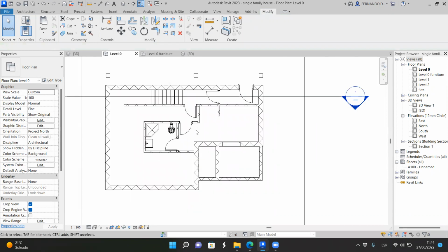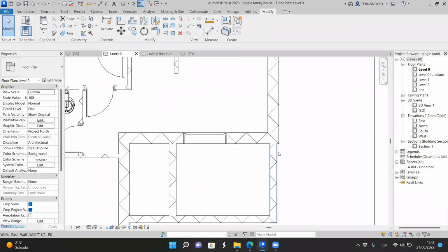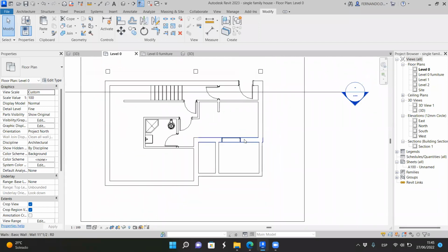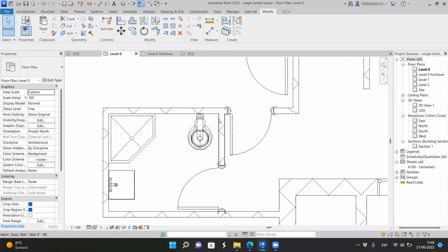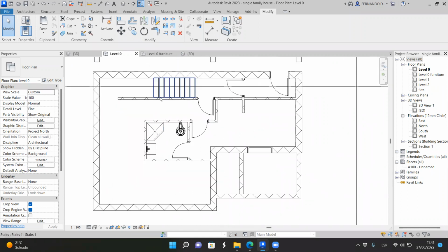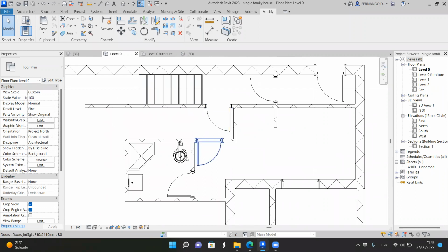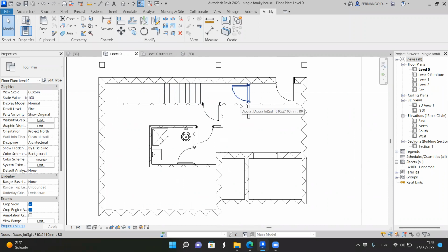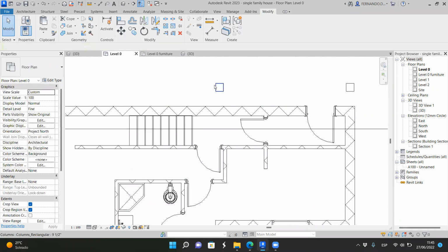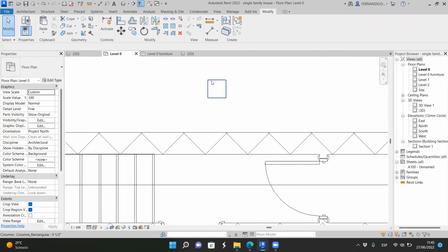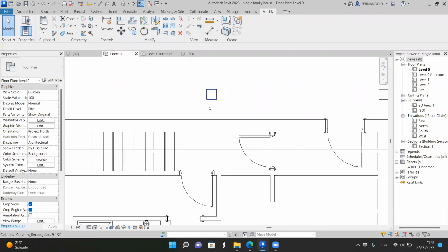And now, well, there are different options we can use with line weights, or we can use with hatches, because we need a difference between something that is an important element, a section element, walls, and something that is not section, like furniture or the steps here. The columns, we have to either make a thicker line weight here, or we can hatch this.